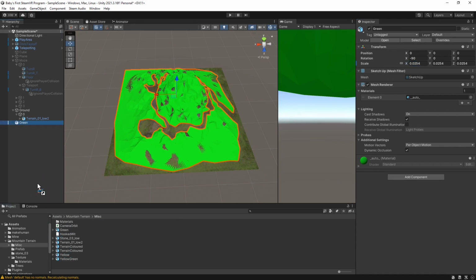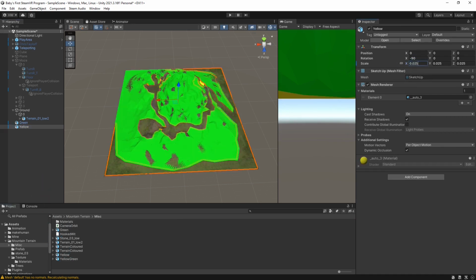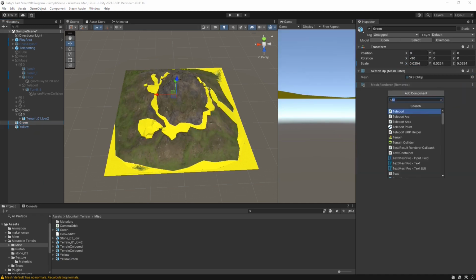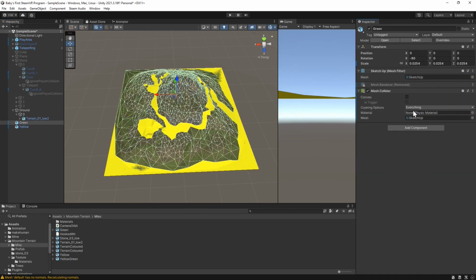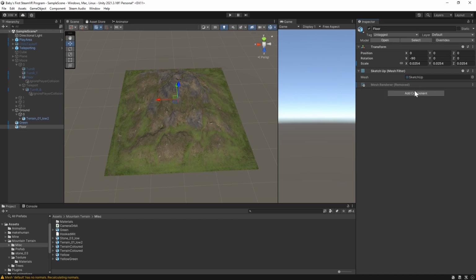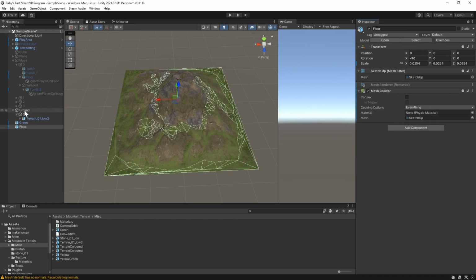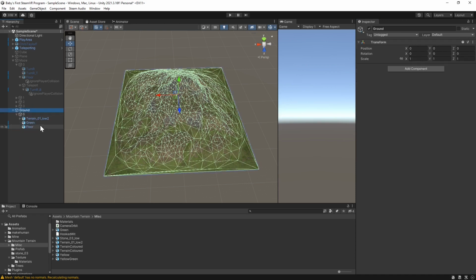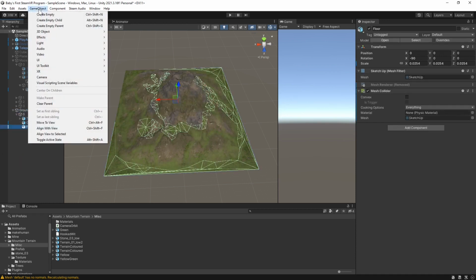Let's import the yellow. Same scale problem. These are in place, of course, for the mesh, not for the rendering. Let's take the green, remove the mesh renderer, and add a mesh collider. The yellow, of course, has to be called floor. Remove the mesh renderer, add the mesh collider. These need to be placed under 0 as well. The floor needs the empty child,